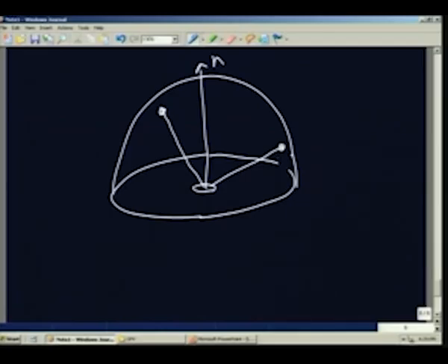We are talking about biangular, that means this is the incident radiation. Of course, this requires very expensive equipment. The goniometer makes it possible to have incident radiation coming in this direction, and the reflected radiation in any given direction can be measured. You will also see that if the amount of radiation falling here is some value, the amount reflected in this direction may be very small.